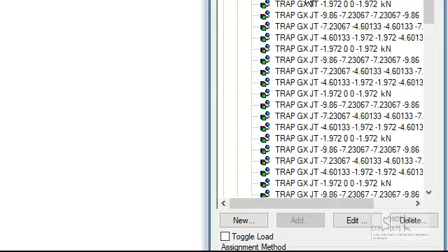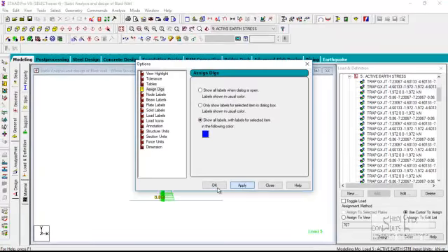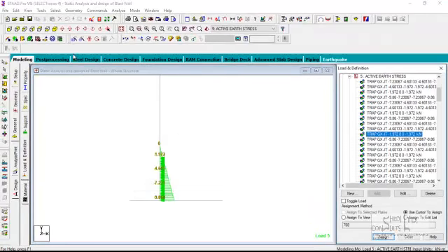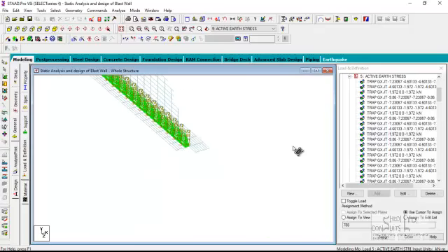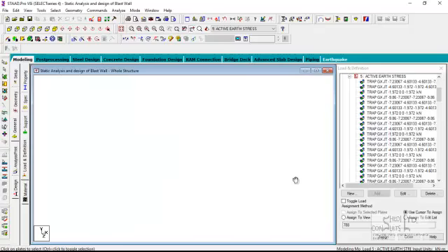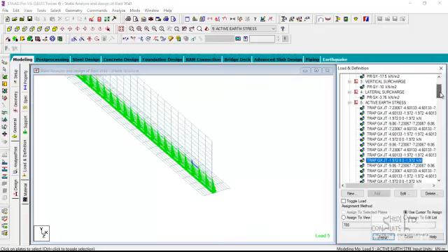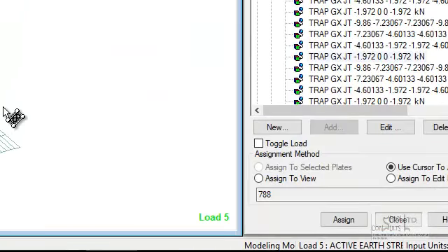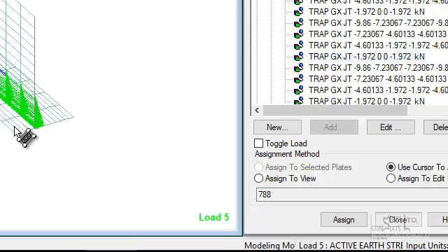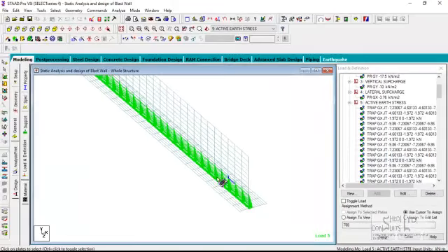And then we have the active earth stress. This is the active earth stress. Acceleration was calculated properly and explicitly, and then it was applied on the wall. Okay, so the active earth stress happens when the soil moves into the wall. So the soil moves into the wall, you have the active earth stress as a result of that soil movement. And then when that happens, you have the mobilization of the passive earth stress as well too, because the wall in return moves into the soil.